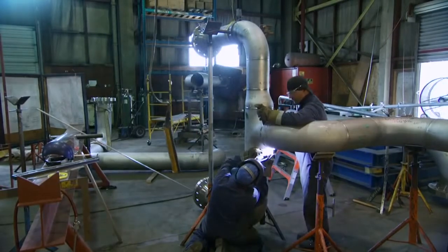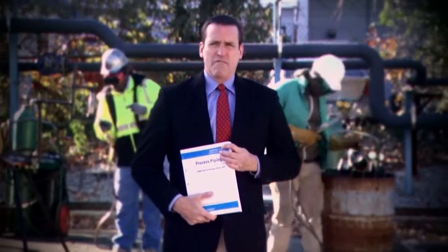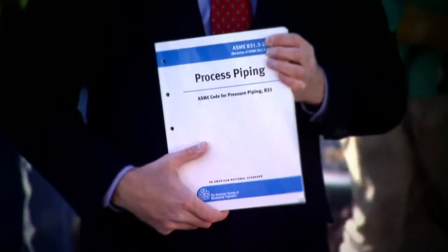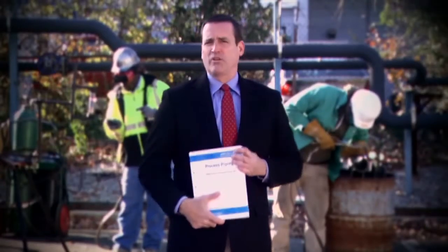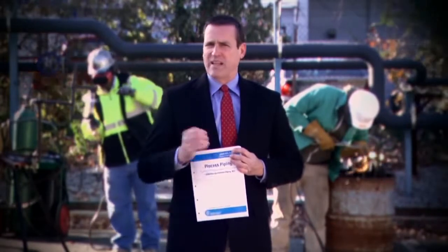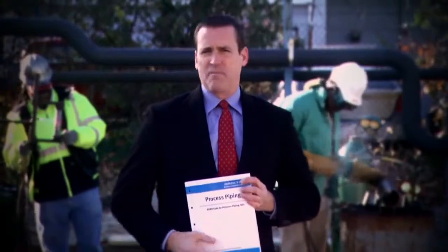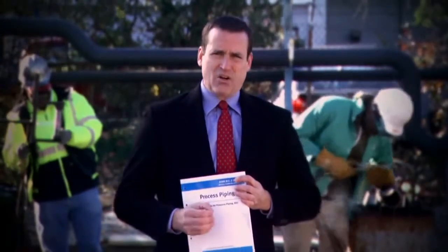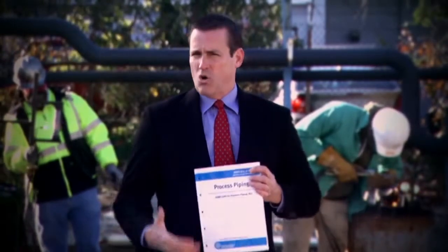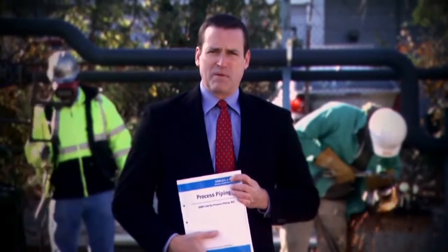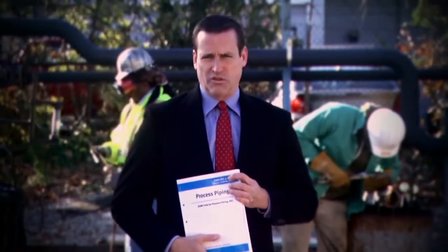lowest possible long-term cost. The American Society of Mechanical Engineers, or the ASME, first published the B31 American Standard Code for pressure piping in 1935. Today, this code consists of several sections and is recognized as standard industry practice when it comes to piping. As such, it provides the engineer with both a technical and a legal foundation for the design and installation of piping systems. Accordingly, the first step in the design of a piping system is to select the appropriate ASME B31 code section for the service conditions.